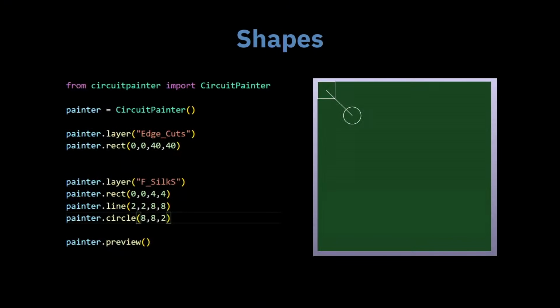And then a little more complicated things. There are shapes. We made rectangles, lines, circles, and arcs. This is an example of how to do it with the silkscreen layer. If you switch to F.Silk-S, that's the layer that puts it on the top. The way KiCad works internally is it has different kinds of things for conductive tracks and things that are just geometry. The versions I'm showing here, with rect, circle, and line, are only making non-conductive things that are visual. But there's also a version like track line or track arc, which make conductive paths. So you can choose both of those.